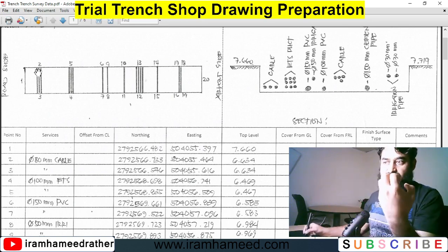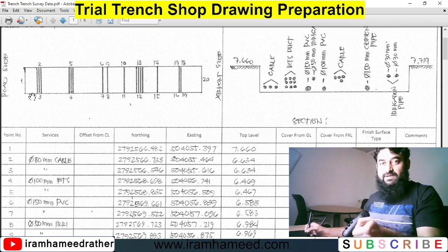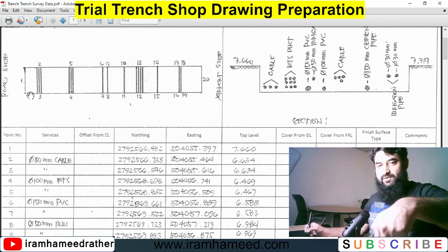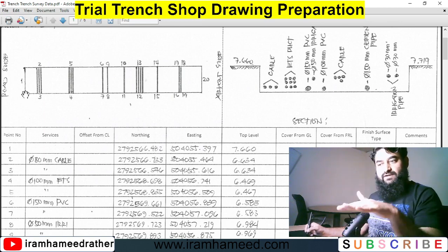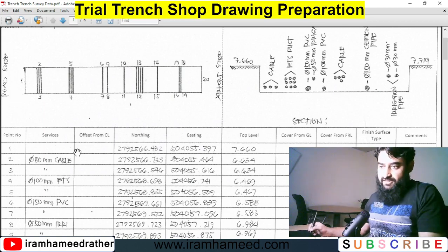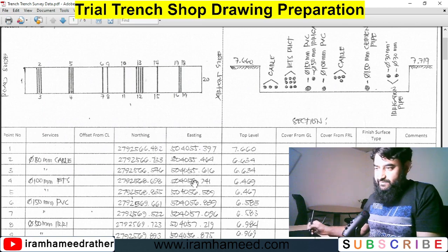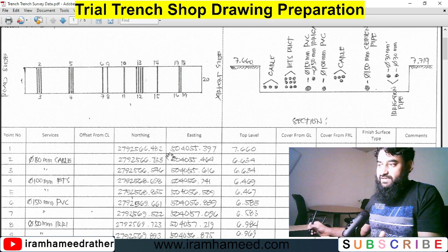They put their prism on this location, exactly on the pipe or that utility, on the top of that cable, in order to know its Z value and its X and Y, easting and northing. So these numbers represent the serial numbers of your points. And here is that information: these 1 2 3 4 5 6, these are your coordinates and these are your elevations.